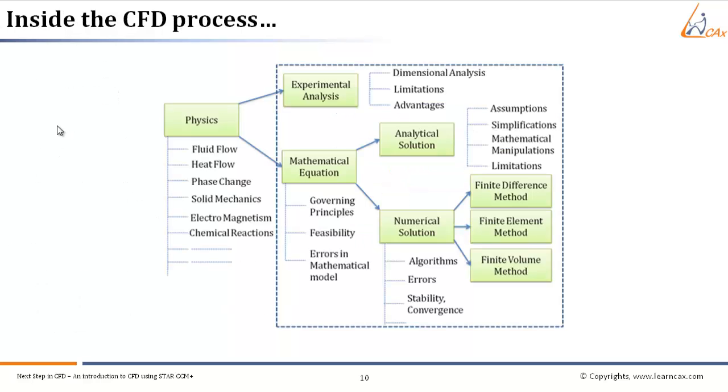Now let us go into a bit more depth on this particular process. Why are we doing all this? We are doing all this to study the physics. Physics may be fluid flow, heat transfer, phase change, solid mechanics, and many more. Instead of going through experimental analysis, we are doing this by mathematical equations, and we are not solving these equations by analytical solution. We are actually solving these equations by numerical techniques, using different algorithms like finite difference, finite element, and finite volume. So this is what goes on inside the CFD process for anyone who is new to CFD.